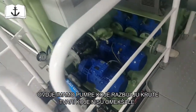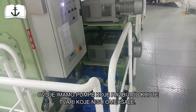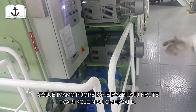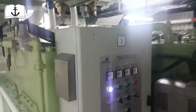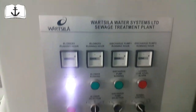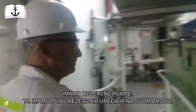And here you have the discharge pump. They call it a macerator pump. It's an impeller. Anything that stays solid gets broken up before discharge. We also have 2 units for redundancy: 2 blowers, 2 discharge pumps. Okay, so there's a lot of redundancy on this ship.